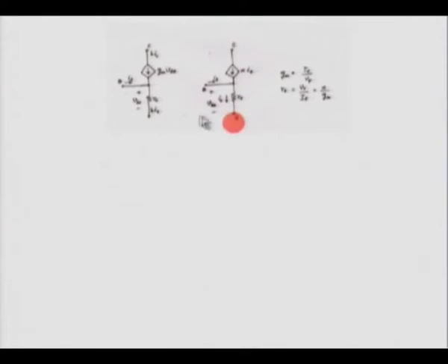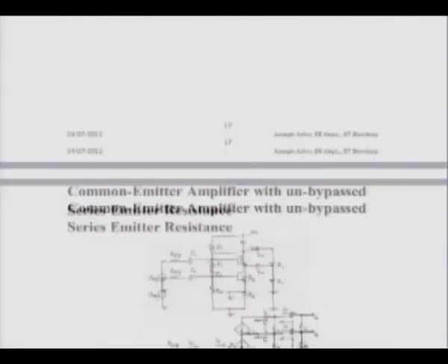That was a voltage controlled current source model, whereas here it is current controlled. Now, in this case, the only difference is the controlled source has alpha times IE. So, the controlling parameter is IE here, and you have a small re. In this model, you need only gm and small re, and gm we know is IC by VT, and small re is defined as VT by IE, the emitter current. So, once again, this would be nothing but alpha by gm. Once we know the biasing, the operating values and the biasing conditions, we can determine these values also.